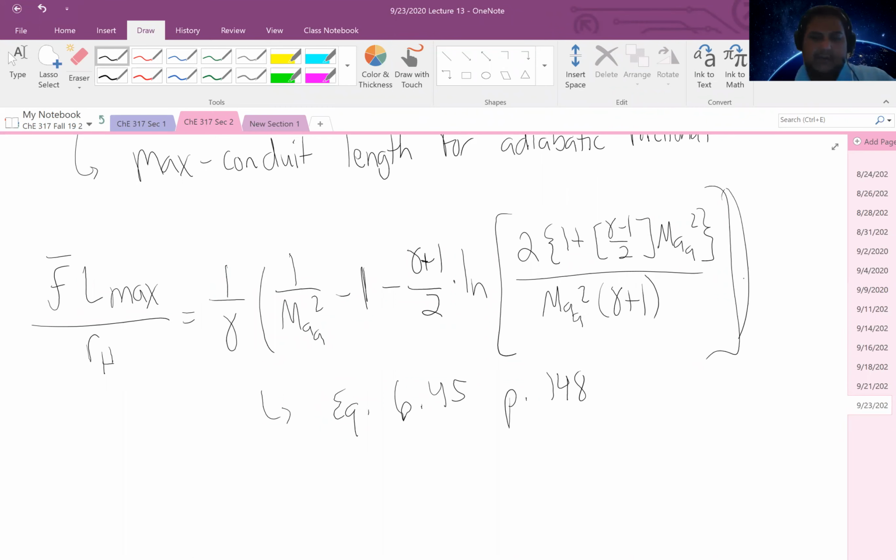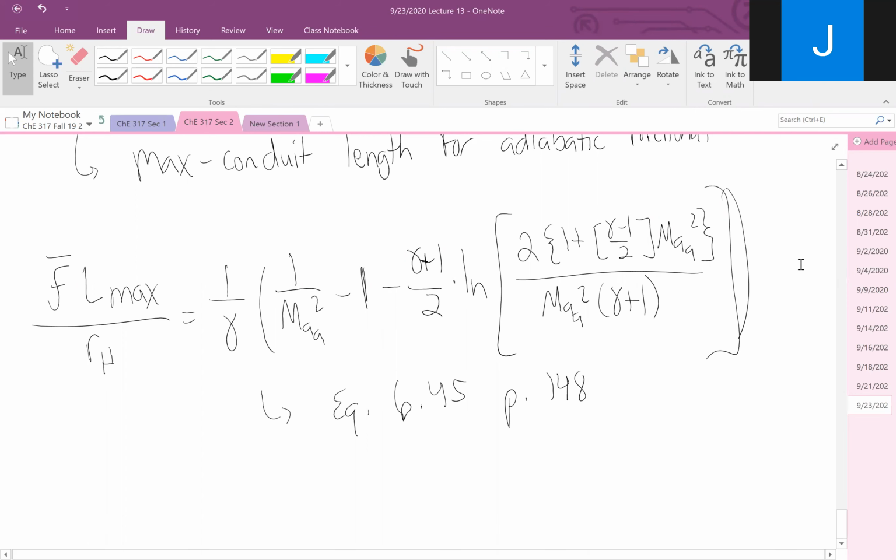Any last minute questions? Yeah, when you're giving the isentropic flow equations for the critical pressure ratio, and the pressure is an asterisk condition, does that mean you can only get your critical pressure ratio if it's sonic flow? Since the asterisk condition would be when the Mach number is 1? Yes. Okay.